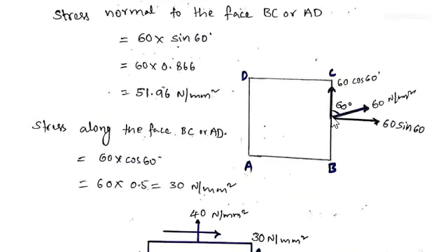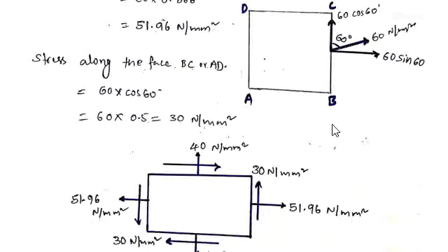So this component of stress will create a shear action. So this component we can treat as shear stress. So on this plane, and if you see one in other direction AD is given like this. So when you resolve, one component you will get like this, and the other component of the stress will go downwards. So anyway it is going upwards, and here it is going downwards. When you resolve that, you will get that value, 13 N per mm square.